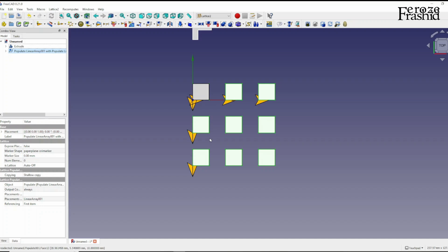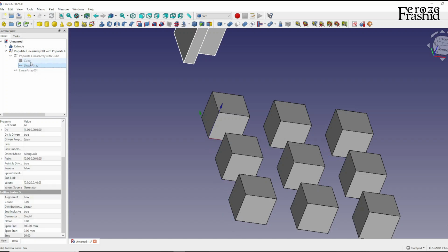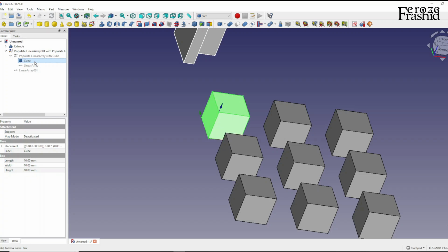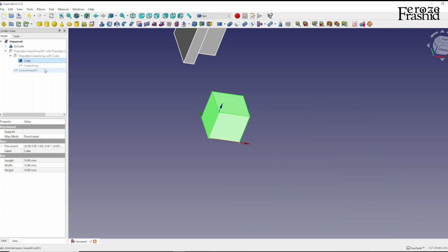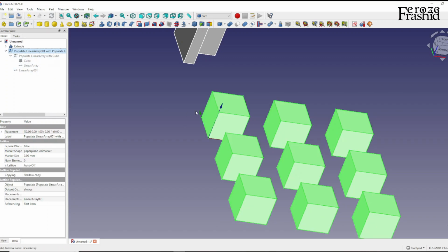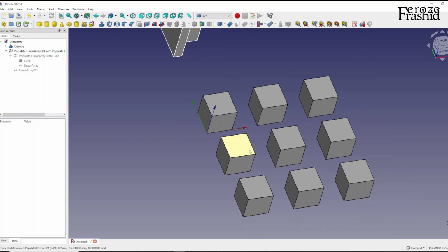So we don't have to sketch the whole thing. We just take one repetitive part and then use the Lattice2 workbench in the linear array fashion. Inside, these arrays are there already. We can hide those, right? And the original cube is there too. If we hide the array and the original cube, we can hide all of these and bring this part back. I'm keeping the axis cross there to make sure we don't lose track of our center.